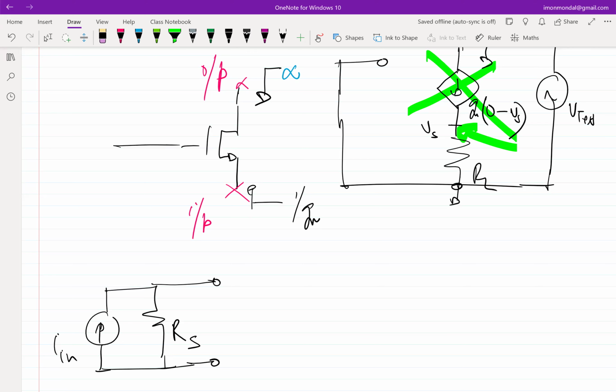Again, I don't want to directly connect, right? Direct connection has those issues, right? If Rs changes, then biasing changes, and so on. I want to capacitively couple. So set up the biasing separately and then capacitively couple. So how do I go about setting up the bias?